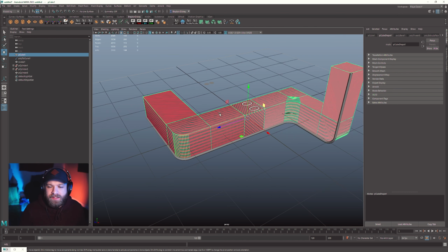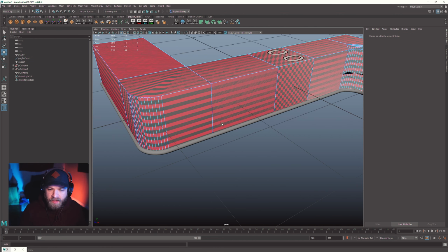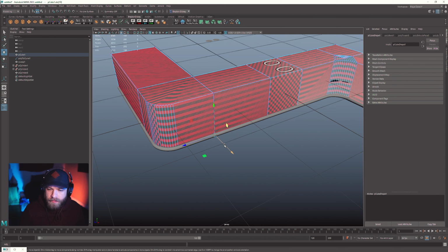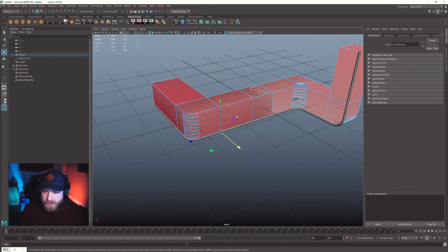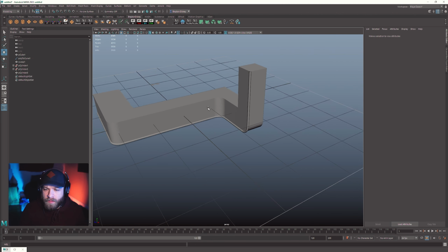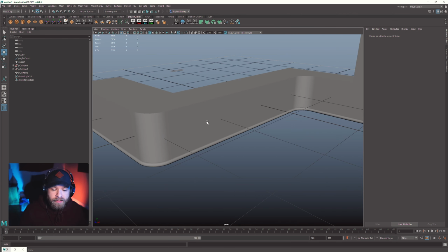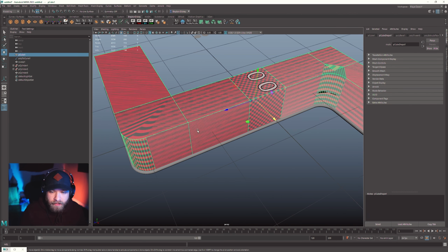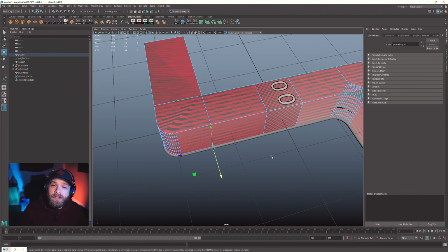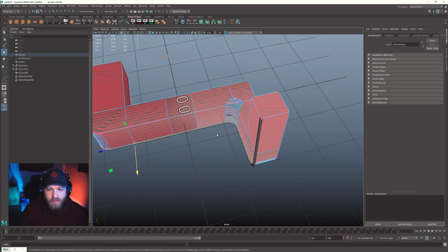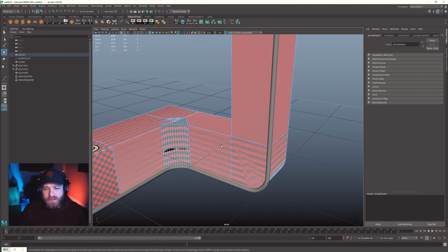is that because that curve originally was made from a piece of geometry, if you edit the geometry, the curve actually gets updated in real time, which means that the tube gets updated in real time. So if you do this correctly and in the right order, and again, you make sure not to clear your transforms or clear your history on any of these objects here, it's all non-destructive and can be redone or changed at any point, which I think is one of the strongest parts of this new tool.